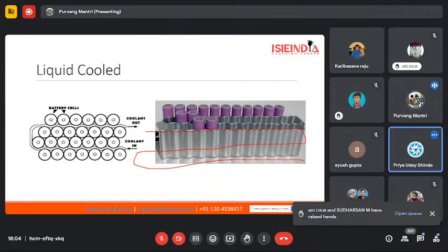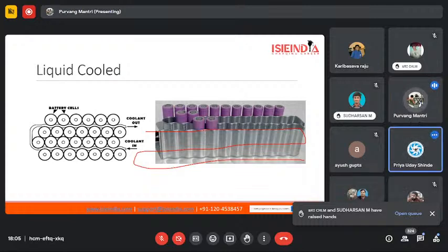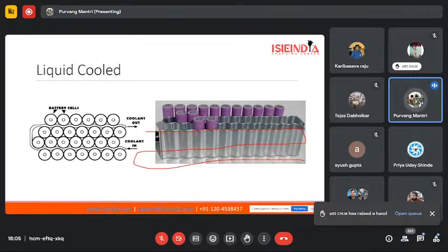But in thermosiphon, the liquid cooling method, let's say for example you are using water, then water will be evaporated and it will travel to another area where it will lose heat. So thermosiphon is actually a good idea to work on, because you don't need to provide any form of pump or any pressurized system to get that water, or that cooling medium, to flow. You're using basically pressure generation, the pressure changes which happen because of the phase changes.